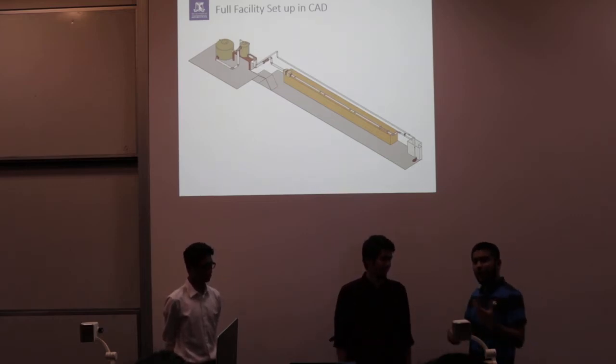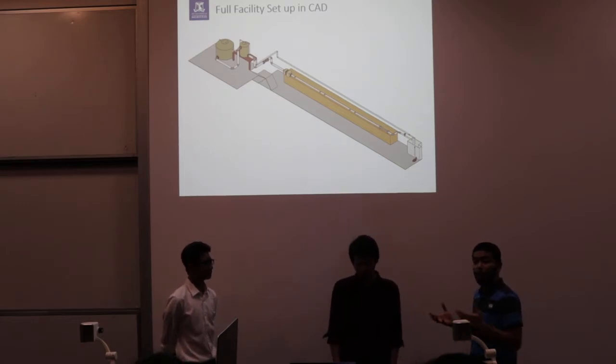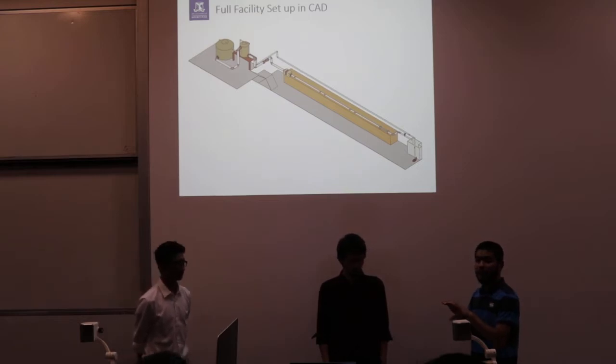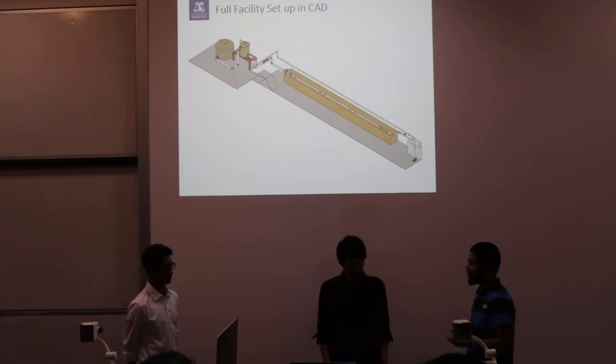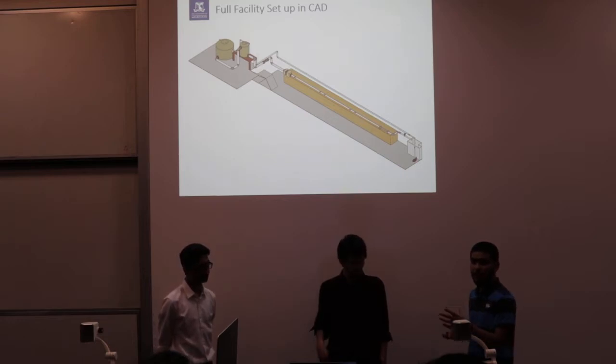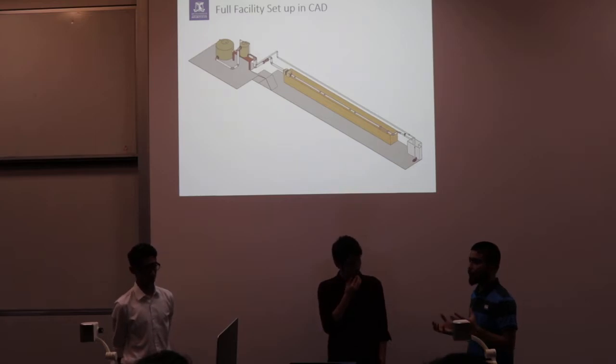I think the main challenge comes when we try to put the parts together, which we are trying to do now. What the pipe needs to be is essentially straight. Our tolerance is 10 micrometers. If there's more than 10 micrometers, what we'll see in our turbulence reading is that it's distorted, so we need further cleaning of our data.